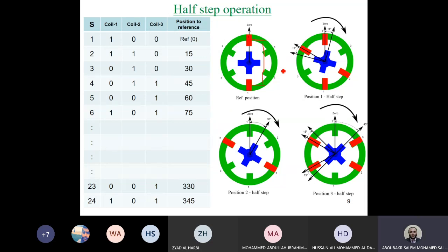However, if you make a permanent magnet motor, which means you will have poles in this portion of the rotor, the flux line will be very short. And from the criteria of flux lines, if the flux line becomes shorter, it will be much stronger. And this can work with higher torque.